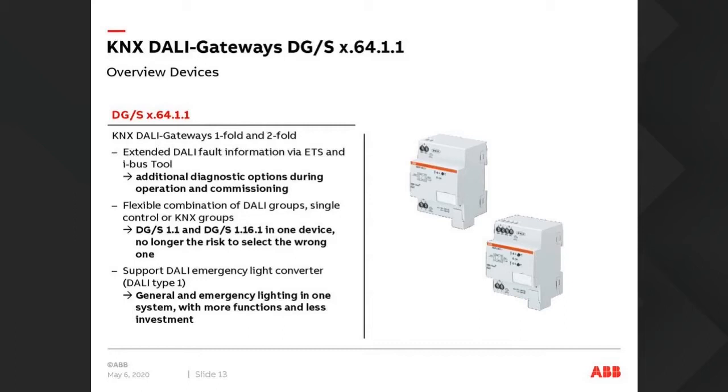So if I have a building with a lot of DALI emergency lights in there, we can connect this up to our DALI bus and we can interrogate these lights. We can do function tests and duration tests and battery tests. The gateway will send the appropriate telegram out to the appropriate emergency device. The device will run its tests as it does in the DALI world, and that's just what it does. And then when it's finished its test, it'll report back to the gateway.